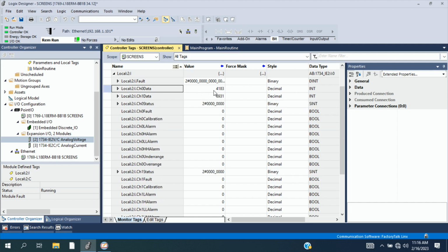So I'm live and running in remote, so I can vary these numbers up and down. It looks like in this case they're going from 0, and as I increment it, it goes all the way up to about 10,364. Interesting, that's about what the voltage was reading, about 10.3-ish on the top end. So it's 10,364, representing 0 through 10 volts approximately.